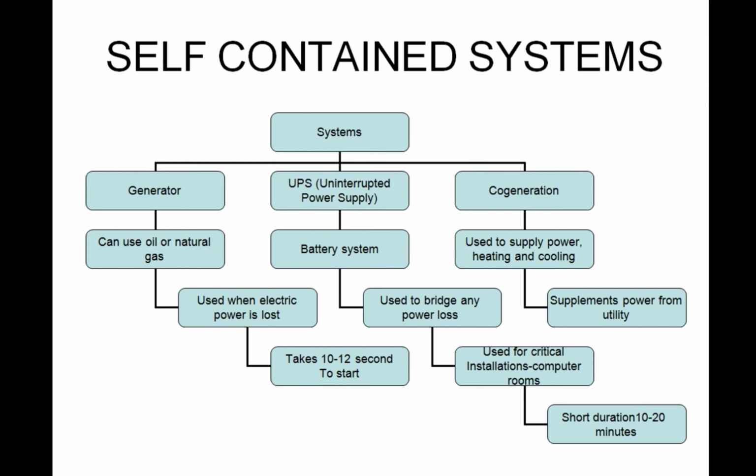So particularly hospitals again. And there were, in the news a number of times, generators that were installed at the hospitals that didn't turn on when they needed to, and you saw those stories in the news when Sandy hit. So the thing is, with the generator, there's usually a startup time required for them, or even if power loss is detected and the generator is set to switch on automatically, it takes a couple of seconds for it to start up and then to be able to produce enough electricity off the bat to power up.